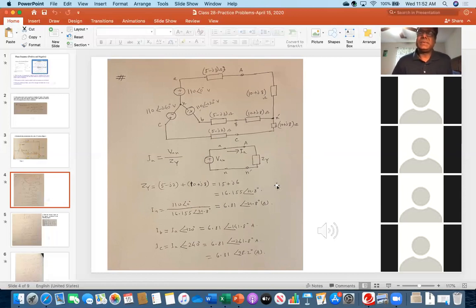So everybody is fine? I have a question. Yes. So are the currents, I guess it's a couple questions actually. So in a balanced system, are all of the impedances on the individual networks going to be the same? Yes. If it is balanced, it must be the same. Okay, got you. So that's why you can just do the angle difference and come up with the current. Exactly.